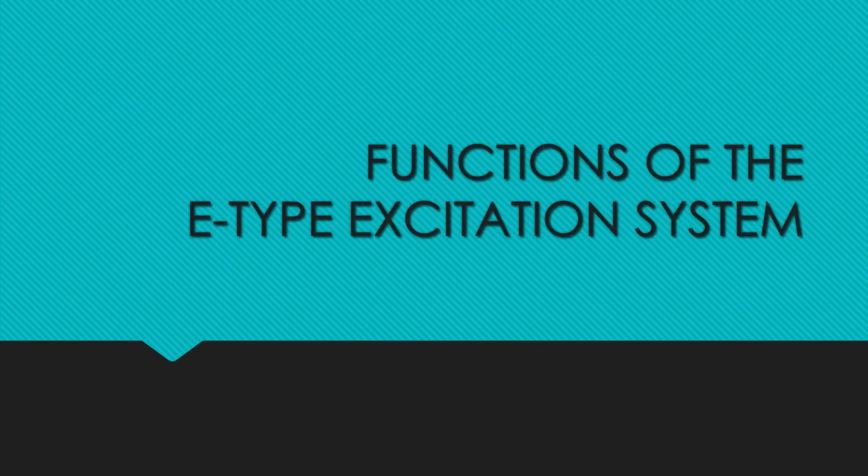Now let us discuss the functions of the E-type excitation system. A diesel engine gives maximum fuel efficiency if it is loaded in such a way that it develops constant horsepower with each throttle setting. In a diesel electric locomotive, the load consists of the traction motors and the current through them varies with the change in speed. So, to keep the main generator power constant, the output voltage must be varied accordingly. The purpose of the excitation system is to ensure that the traction alternator demand matches the capability of the diesel engine throughout its entire speed range.